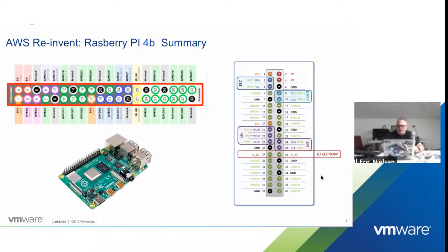And then they have EEPROM. So EEPROM is the ability to program and store data. So if your project, Little Robot, or whatever you're building has data that you want to store for configuration in the chip, you can put an EEPROM on it. A lot of different devices have EEPROMs built in. With Ethernet cards, generally the Ethernet chip will have an EEPROM next to it, so that when you configure that Ethernet, the EEPROM gets written, so that every time you reboot that machine, the Ethernet has its own settings already pre-configured for that machine. So that's what EEPROMs are used for when you're building hardware.